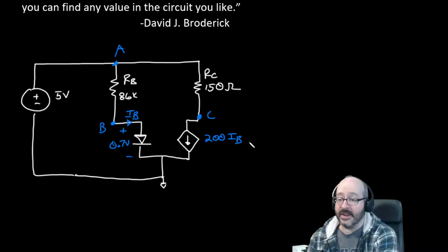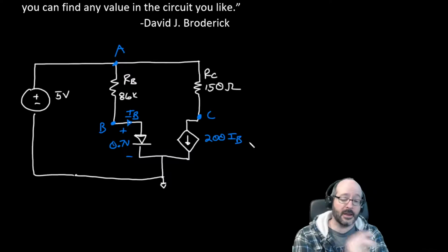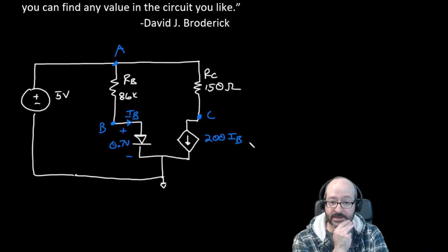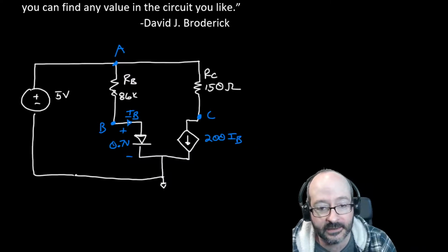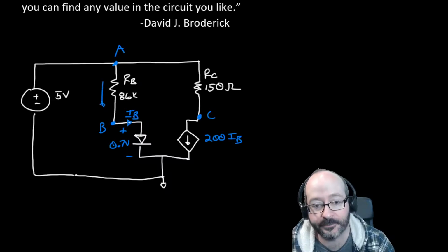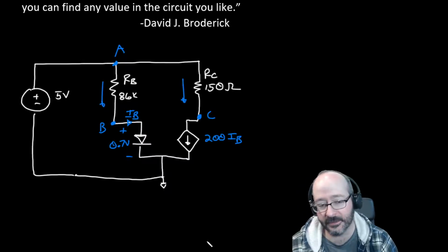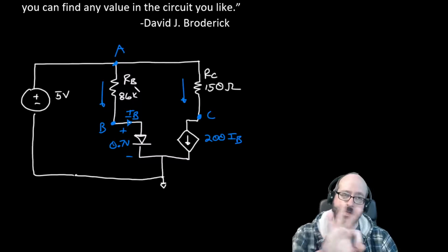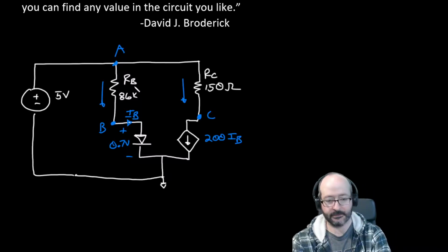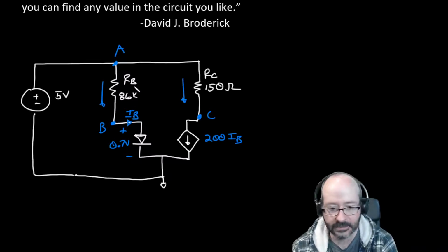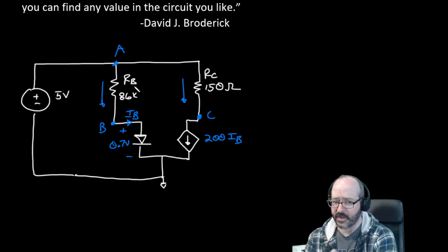Now we just do circuit analysis on this, and you can do it any way you want. I'm suggesting you should think about using nodal, and you'll be a lot happier in the long run. We'll use MATLAB to do the rest of it. I've got three non-reference nodes, so that means I have 3 unknowns, and that means I'm going to need 3 equations.